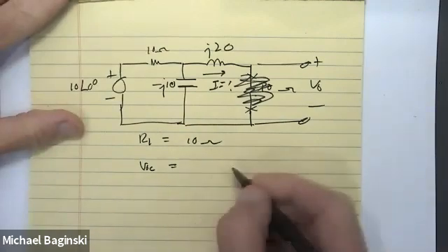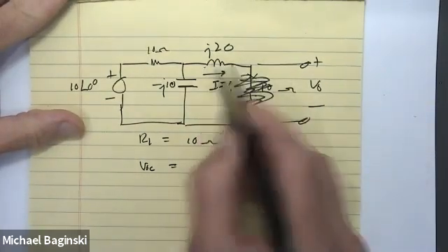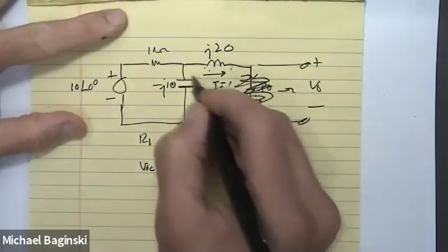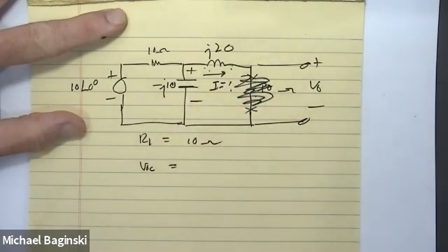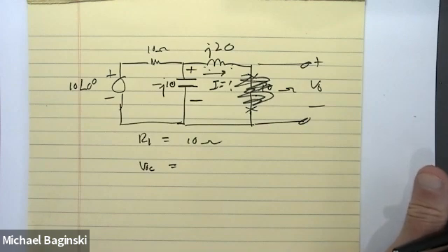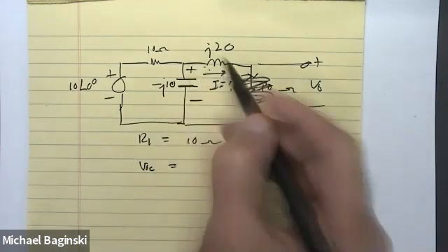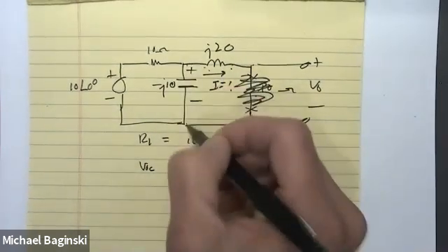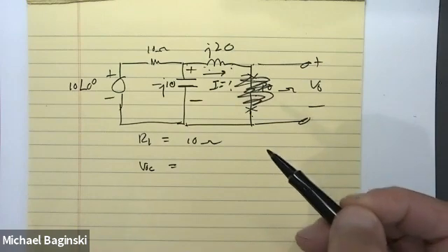All right. So now I want the open circuit voltage. If no current is flowing there, do you all see that the open circuit voltage is the voltage across that capacitor? Can you see it in the back or not? You understand what I'm saying? If there's no current through here, then literally this voltage is this voltage, right? There's no voltage drop across the inductor.